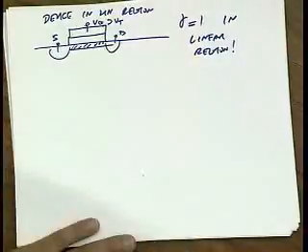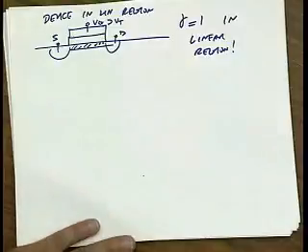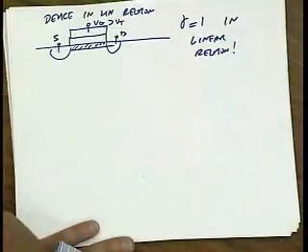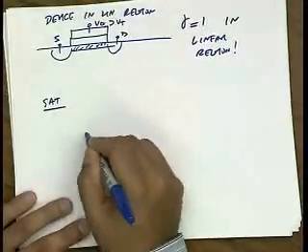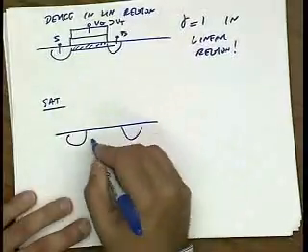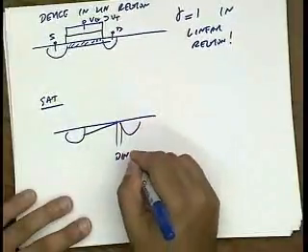Yes? The first equation, GDS0 is defined when VDS was 0. That's right. But the equation applies to the case of the saturation region where VDS is higher than 0. That's right, yeah. So the idea is that once you go into saturation, you have this pinch-off region, right?